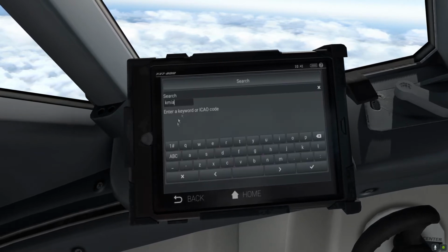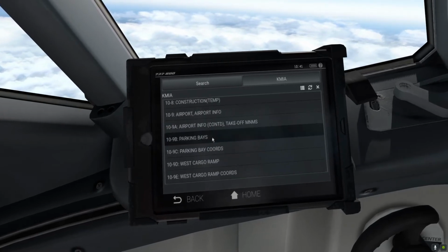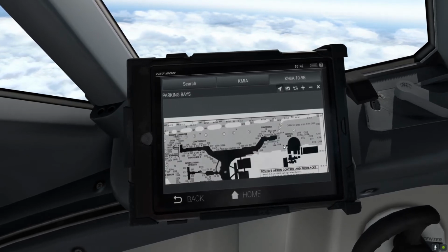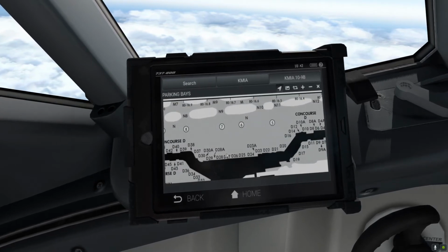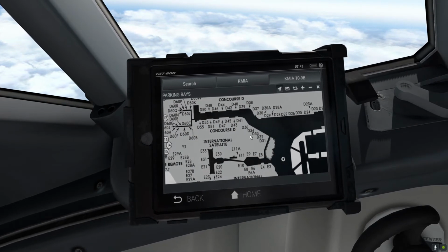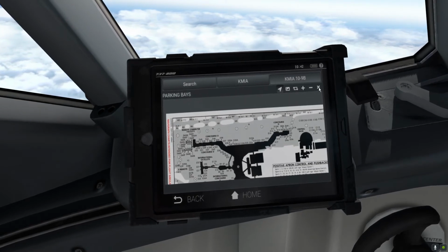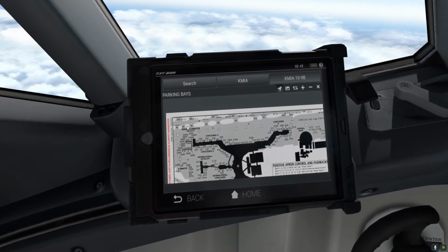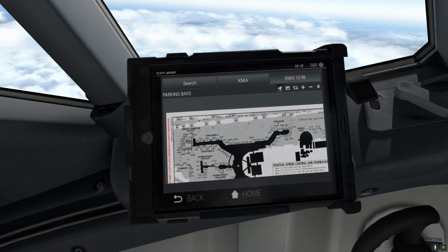And then we are going to park here at the expected arrival gate at Delta 34, which is down here, Delta 34 here at Concourse Delta, American Airlines Concourse Delta in Miami. So we're gonna land up here and then vacate to the right, cross runway 8 right, and then most probably by Mike and November 4 we join Delta 34 parking.